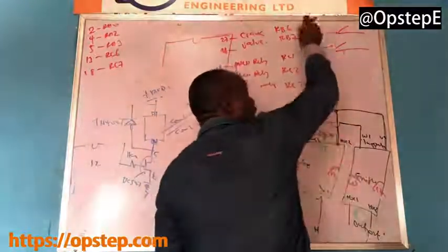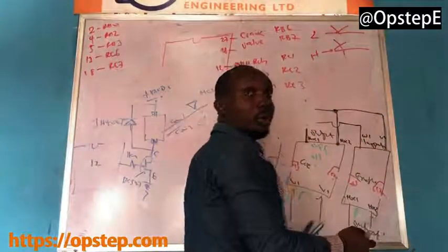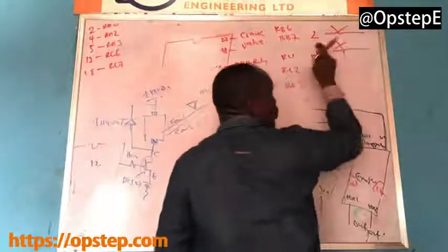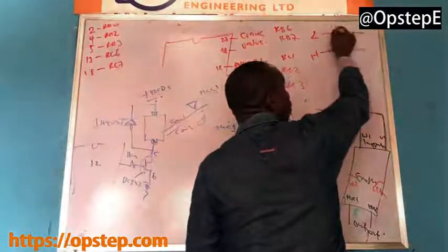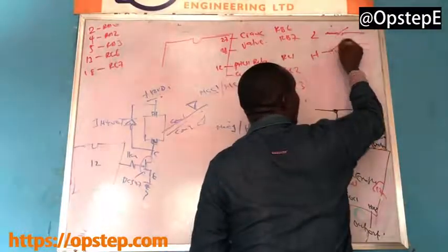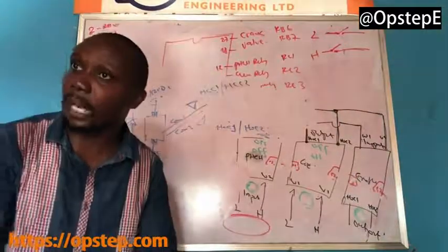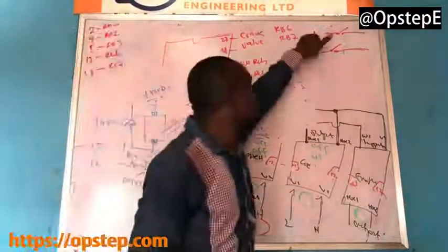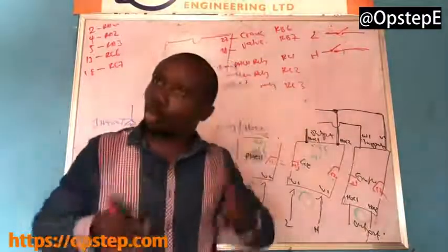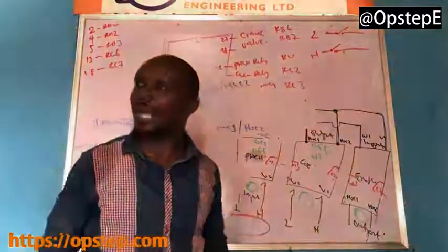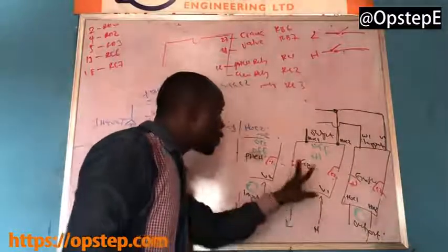So when you enable the coil, what happens? The two latches. Are you with me? So that live crosses to live side, neutral crosses to neutral side. And when you remove the coil, what happens? They are open again. So that's a gang effect, which means it's happening at the same time. It's not like maybe if you close live, you don't close neutral, there's still no light. If you close neutral, you don't close live, there's still no light. The two must be closed, satisfied at the same time. That's why you have live neutral here, live neutral here, and live neutral here.